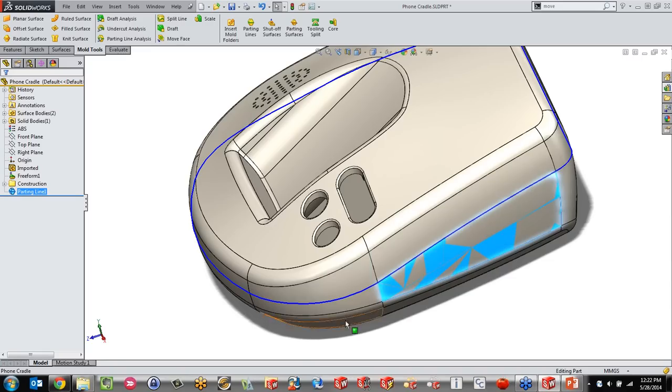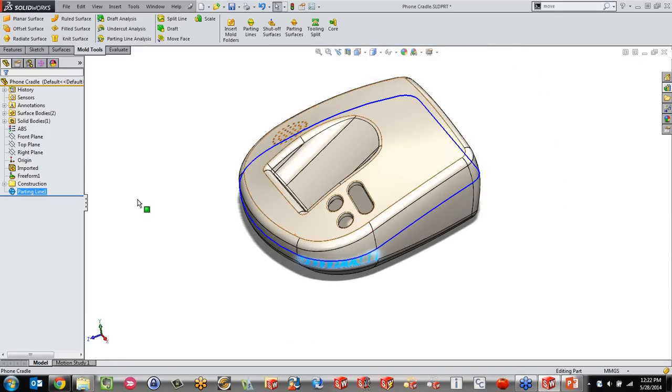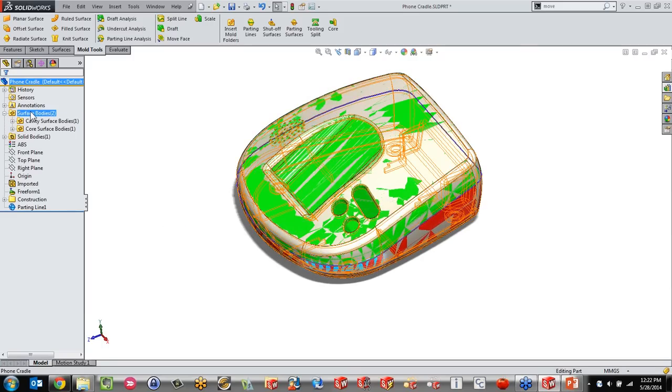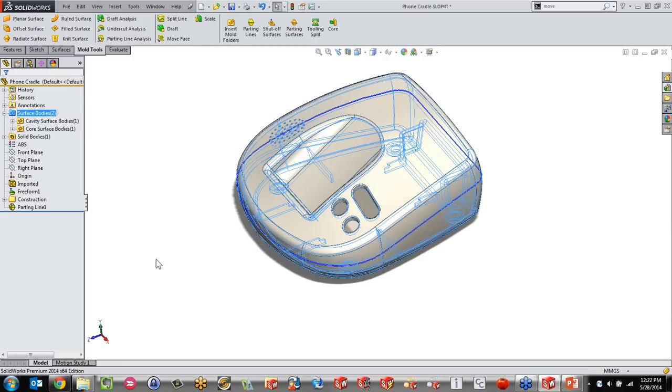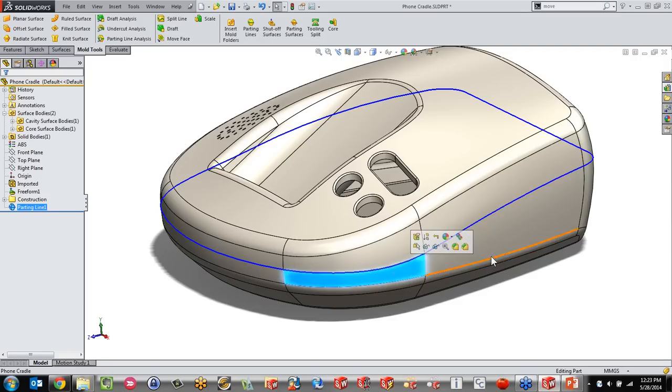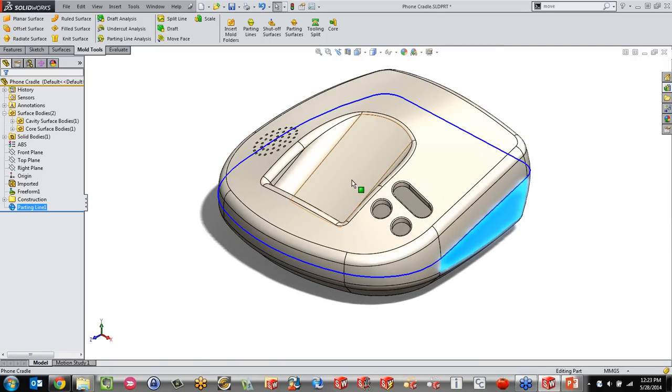I've just split the faces on this part and created those two surfaces that are roaming around the part. Now, with that, I split the solid faces. I still have to break the model into two pieces, because if you've got to make a mold for this, it would need to be two cavities and two cores.